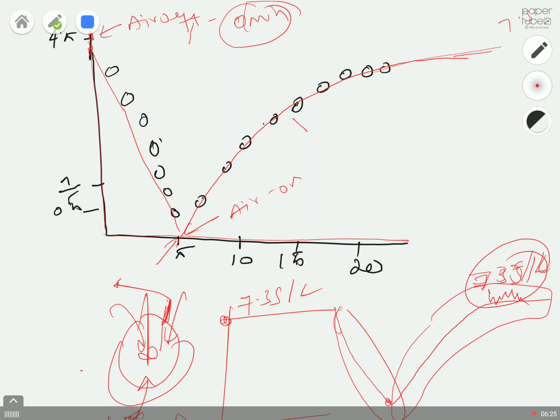So at this part, there is no oxygen transfer rate, only oxygen utilization rate, because you already cut your oxygen supply, which means you are not transferring anything, but your microorganisms are consuming your oxygen. So this slope corresponds to oxygen utilization rate, and this one corresponds to oxygen transfer rate. Oxygen transfer plus some of your microorganisms will continue to utilize your dissolved oxygen in the liquid. So that's the whole concept.